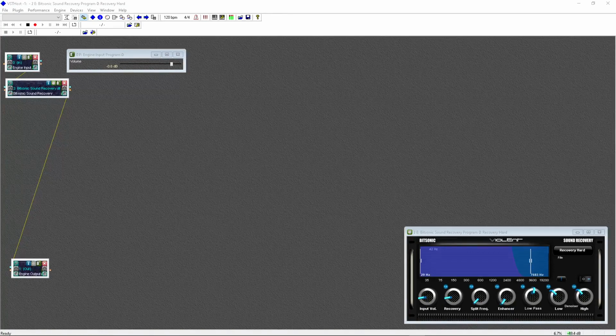And let's click on a signal here. So what you want to do, if you're on a conventional transceiver, is set your RF gain to about 50%. All right. If you're on an SDR, set your AGC to RF gain open. I tend to run mine fairly open, and I let this system take care of the noise. Okay, so I'm going to click back up here because this is a good signal. I think this is a net going on or something.